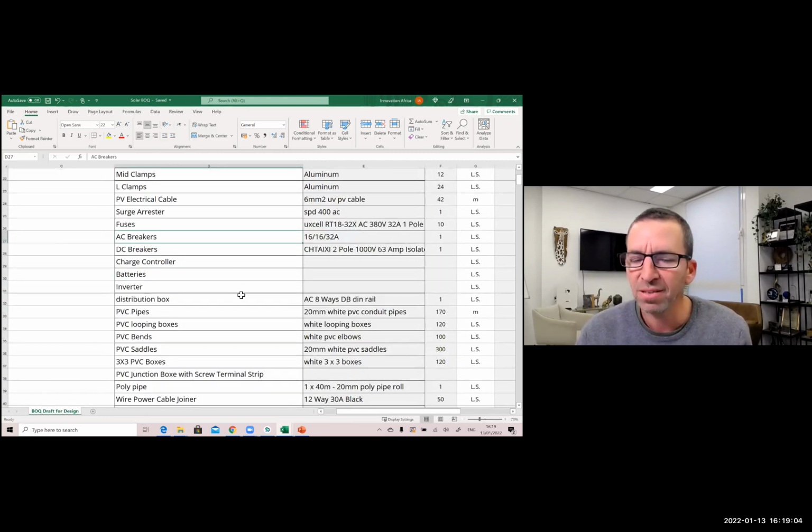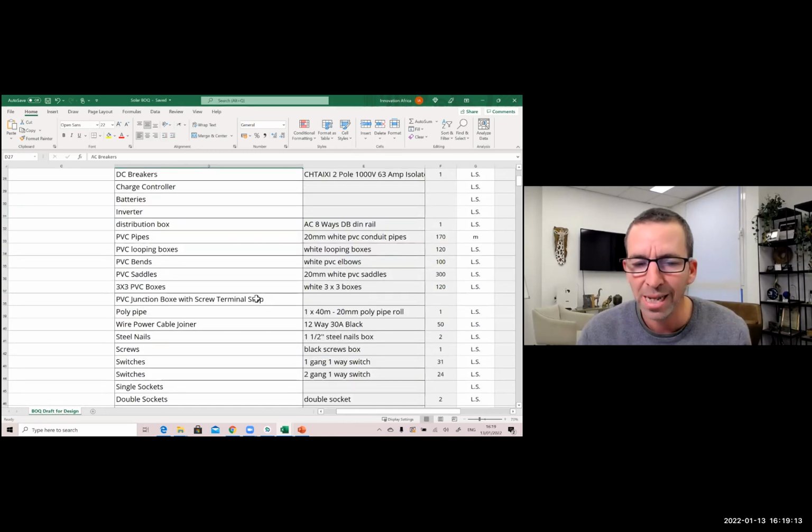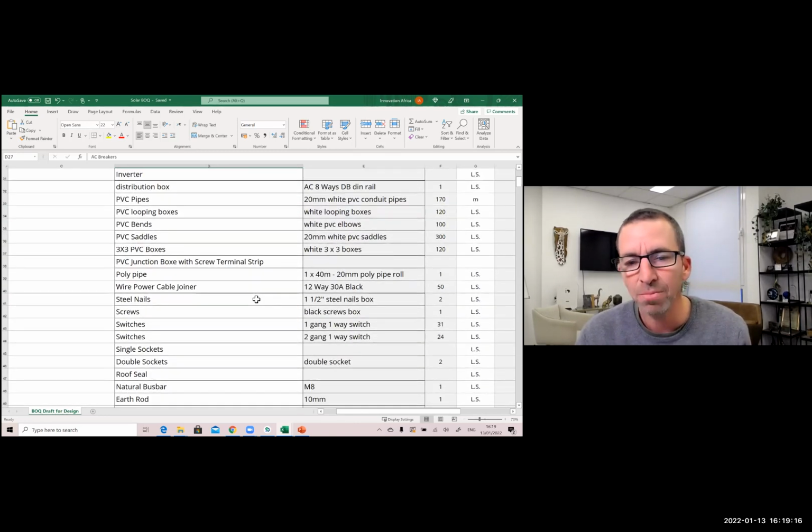Meaning that if the design includes a lot of wiring cables, and you see in the BOQ that the contractor didn't put enough according to the design, it might cause, again, not for certain, on-site problems where you come to the site and you don't have enough materials because the contractor put insufficient equipment or components, and then you have to go back, or the installation is not as good as expected.